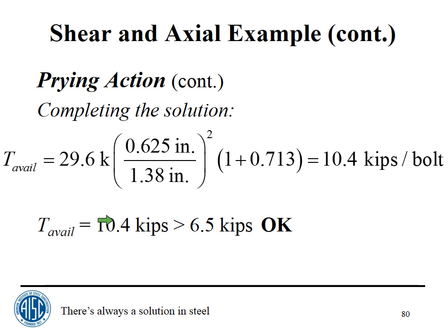It would be nice if we could fabricate our own angle. We could come up with the thickness that we need. But 5/8 is what we're stuck with. Well, maybe there are angles to the nearest 16th. I don't know. We never use them. We use quarter. We use sometimes 5/16. We use 3/8. We use half, and we use 5/8, 3/4, 7/8, 1. There's other angles, but those are the ones that most fabricators stock.